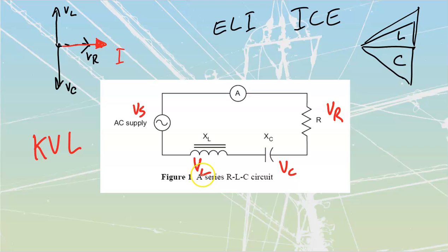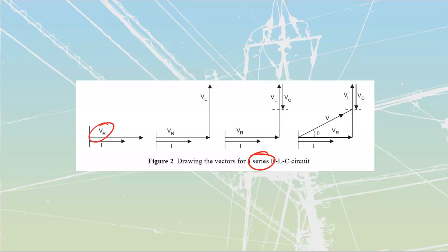We looked at that in both inductors and capacitors separately, that we could just add them straight up because we came to values that were greater. But as soon as we put them in at the proper, 90 or 0 degrees, they totally worked out for us. We're going to do that again. That vectorial addition is really what we're seeing inside of these ones that they have over here, where they're going to take each of those individual vectors, VR, VL, VC, and they're going to add them tip to tail, as we've done before.